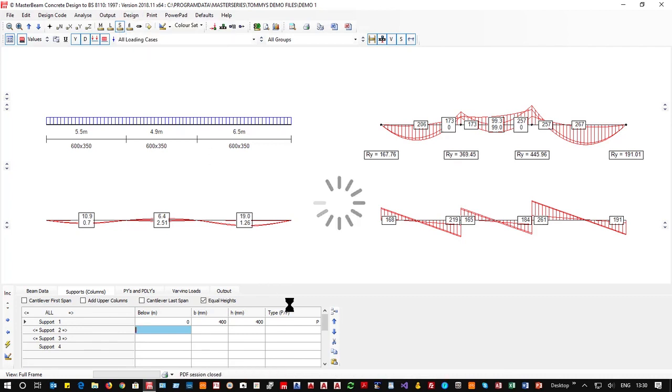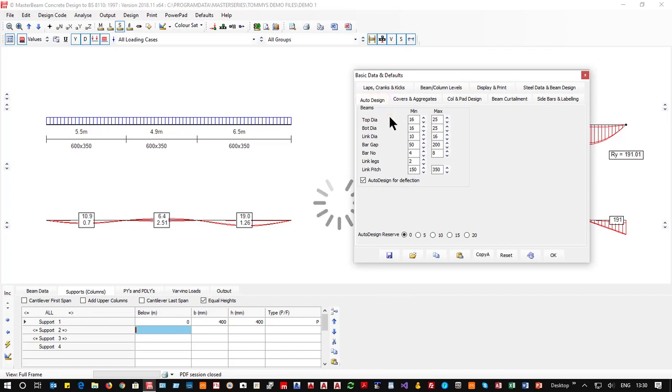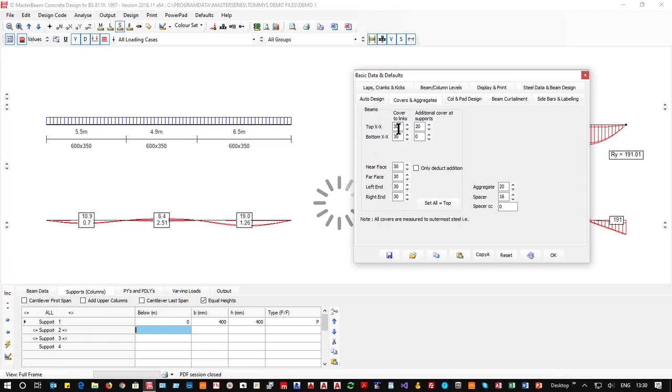Concrete design. A wee bit of setting up to do in this, because we need to tell it a couple of rules. First of all, I'm going to walk from left to right. When I'm doing my design, I'm going to work for 16s, and I'm going to work with 4 bars, and I'm going to try and work with 4 bars throughout with 2 legs. I am going to accept 30 cover because it's not a ground beam in this case. I don't have any columns and pads.